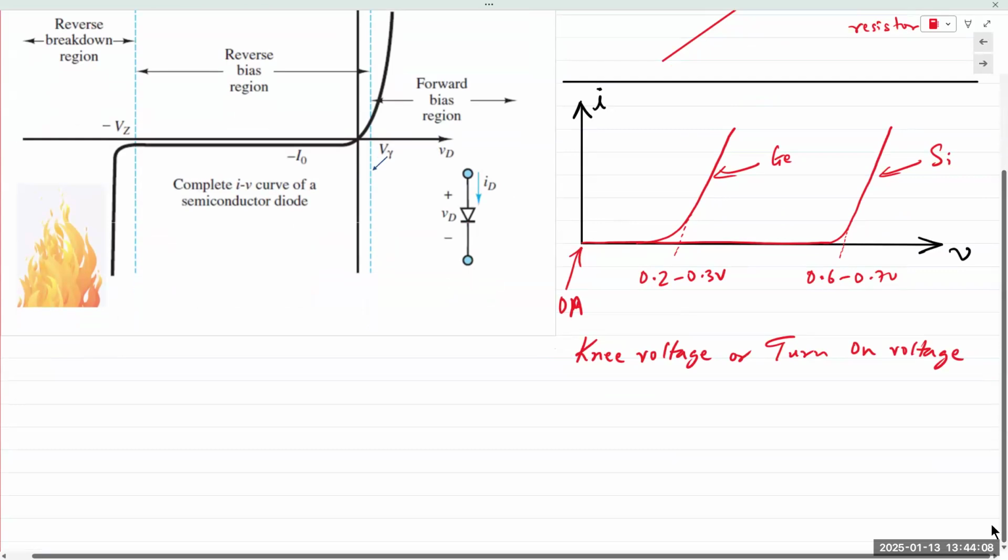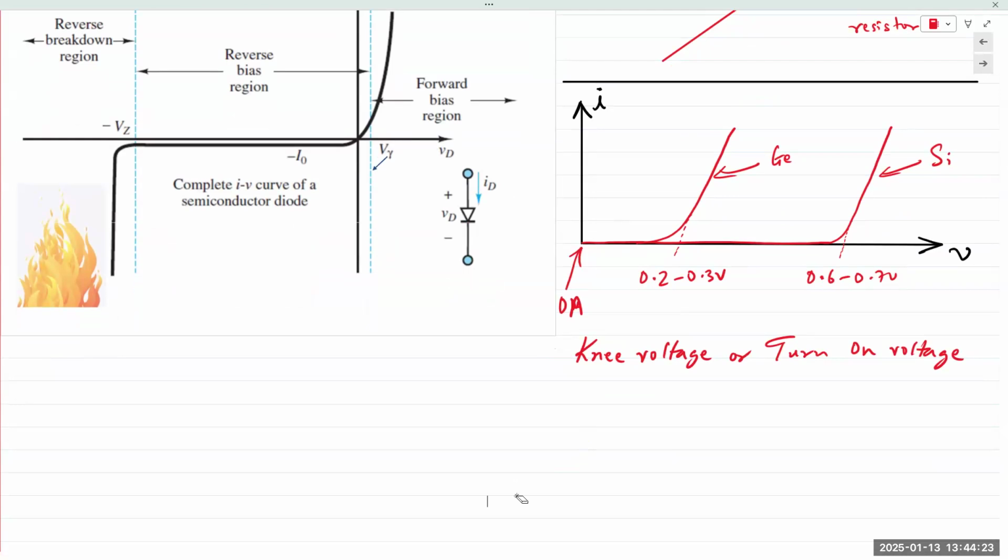And so this is the forward bias VI characteristic. Typically, you would just see something like this, a line going straight up. But the point is that it is non-linear. If you look at the characteristics, even if you keep increasing the voltage, it remains zero for a long time. And after it turns on, current increases rapidly, meaning for a small increase in voltage along the x-axis, the current increases by a large number. From that point on, it is at least linear. Overall, it is considered to be non-linear, but the portion after it turns on is typically linear.